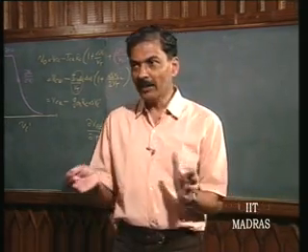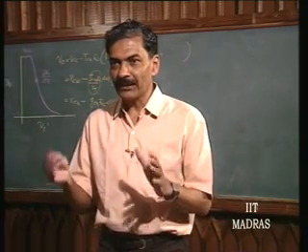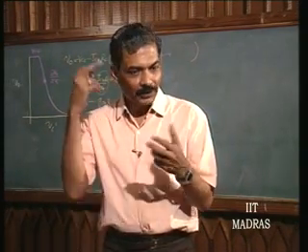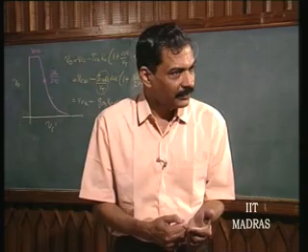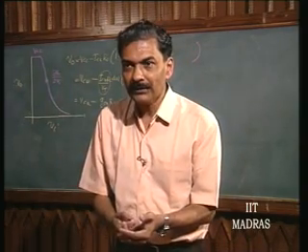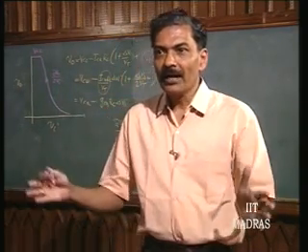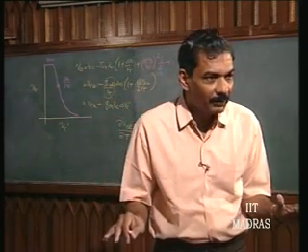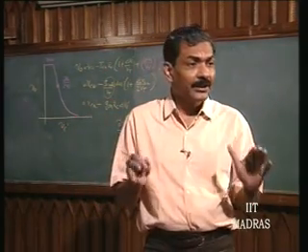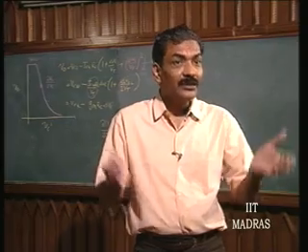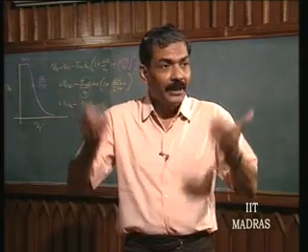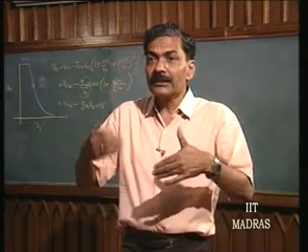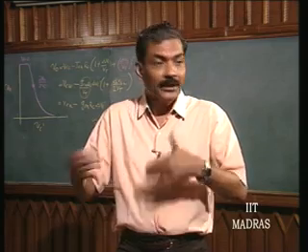So, when you are adopting a common emitter amplifier for IC version, we want to get rid of the bypass capacitor, we do not want the coupling capacitor, and this is one way you can get rid of the coupling capacitor as well as the bypass capacitor in any discrete circuit. This is one important powerful technique of converting every discrete circuit into an integrated version.